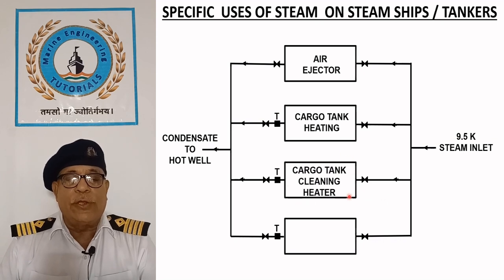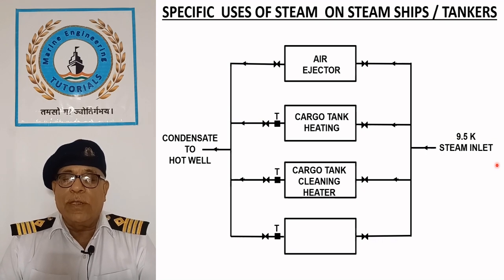Cargo tank cleaning heater. Cargo tanks are cleaned using hot seawater, especially when changing cargo grades or preparing the tanks for inspection or repair. Steam is used to heat the seawater, typically at 9 bar pressure.